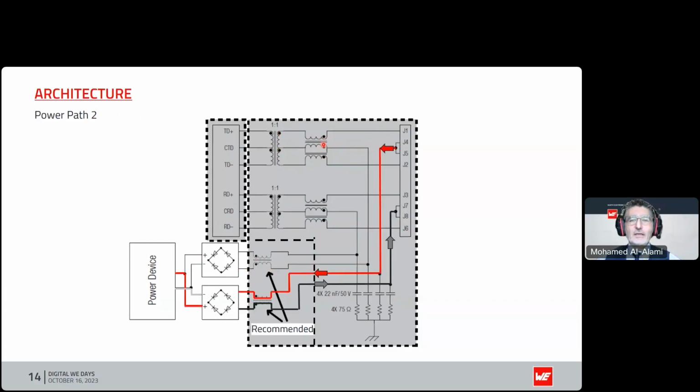Okay. Let's look at path number 2, which is through the spare pair. So exactly the same thing happens, but in this situation, those spare pairs are not carrying any data. This is a 10/100 system, but like I mentioned before, this could be a 1G or a 10G base T, where these could be actual data pairs as well. No difference here whatsoever. Cool.